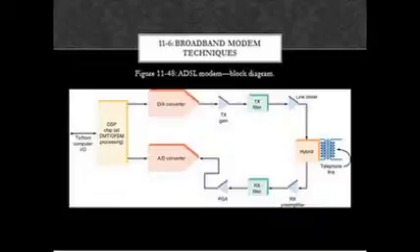The modulation is handled by the DSP chip. The digital output of the DSP is converted to analog by the D/A converter. The resulting signal is amplified, filtered, and sent to a line driver that applies a high-level signal to the line. The hybrid is a circuit or transformer that permits simultaneous transmit and receive operations on the telephone line. The transformer matches the circuit impedance to the line.